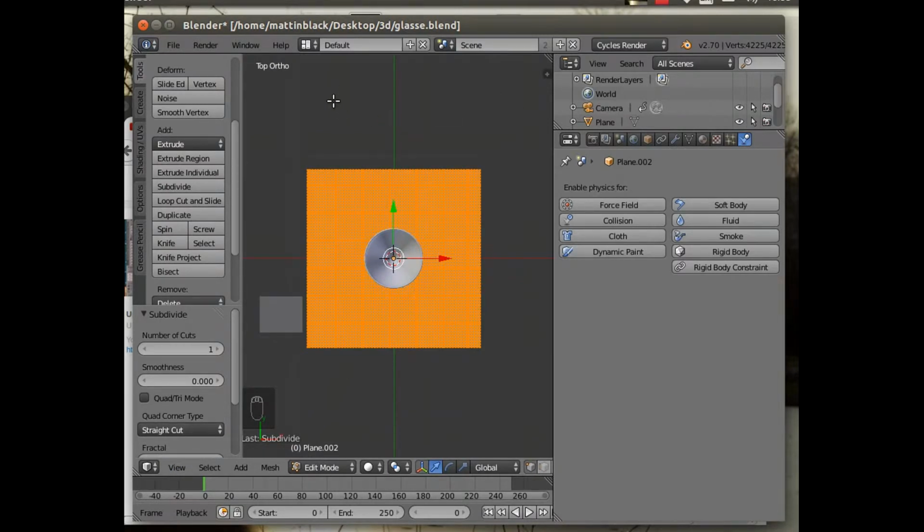Now online you're going to be able to find lots of pretty material pattern textures. I've found one which I quite like, so that's the one I'm going to use. You can also make your own. You can photograph a tablecloth. There's nothing to stop you from doing that, so long as you do it dead square on from the top, as if you were viewing it like this.